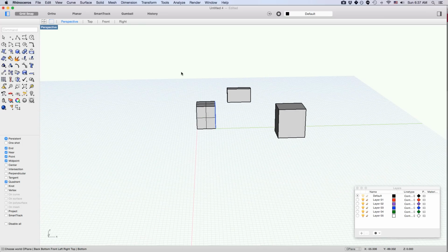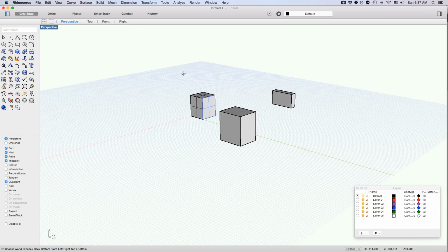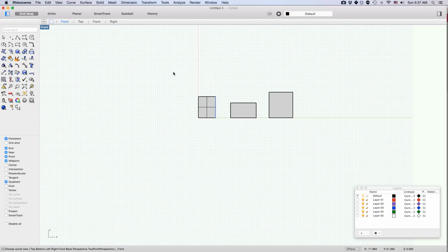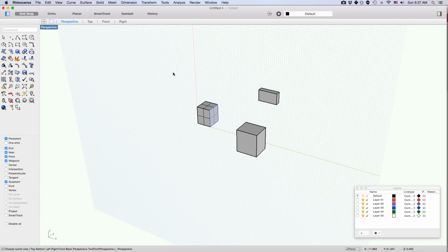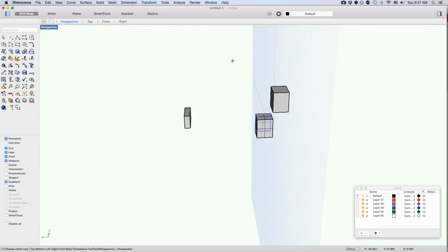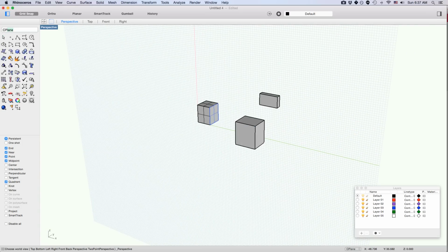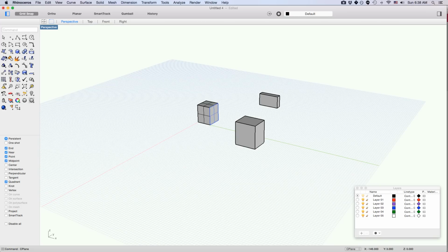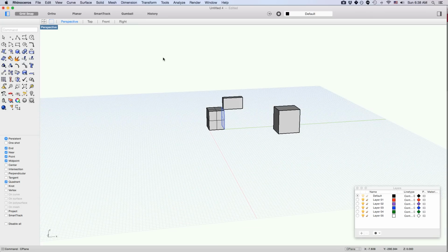Now I'm going to demonstrate how this works in Rhino without the short keys. I'm going to go back to front view again, and then go back to perspective view, so TT space. I was at EE space and I did TT space, now in the perspective view, and now my grid is vertical like this. I would need to type in C plane, click on world, and go to bottom in order to do the same thing as just pressing RW space. So that's how much short keys can save in terms of time and effort.